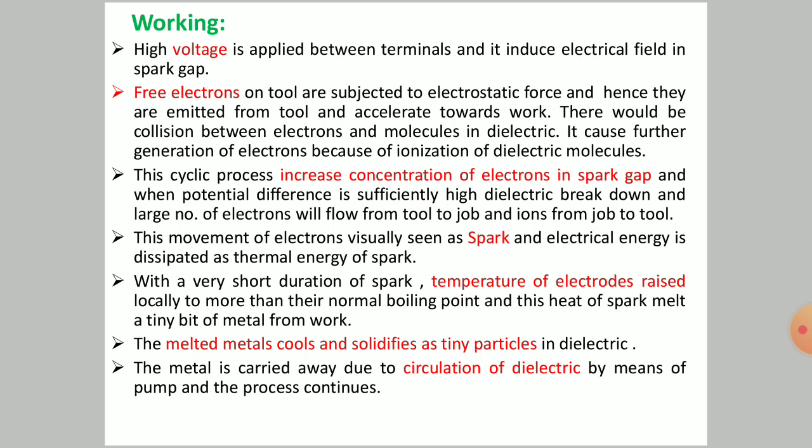With a very short duration of spark, the temperature of the electrodes is raised locally to more than their normal boiling point, and this heat of the spark melts a tiny bit of metal from the workpiece. The melted metal cools and solidifies as tiny particles in the dielectric. The metal is carried away due to circulation of the dielectric by means of a pump, and the process continues.